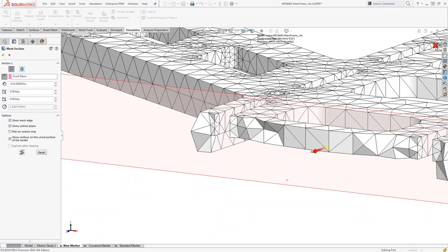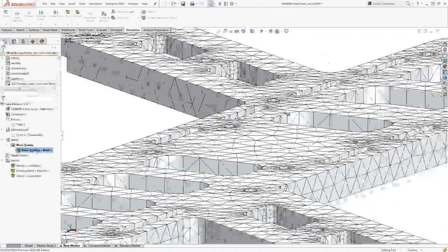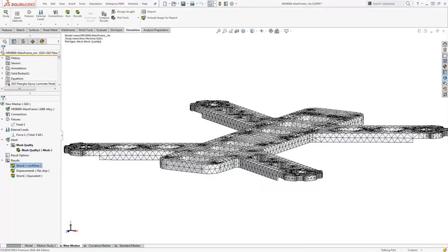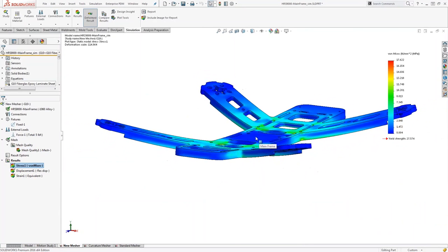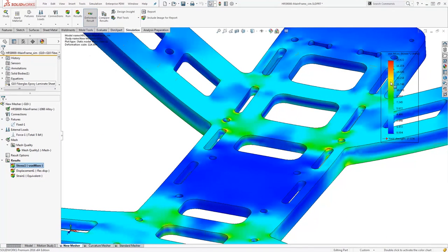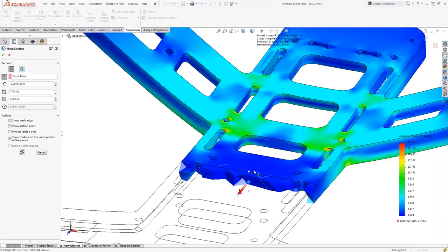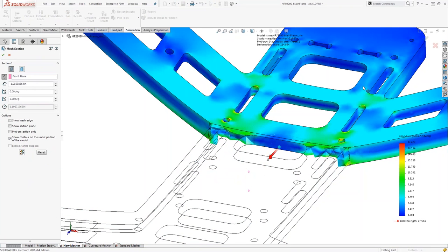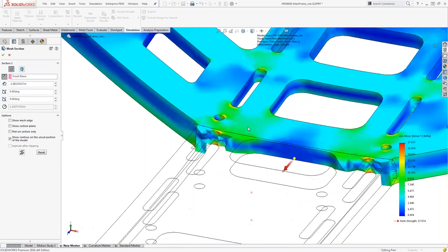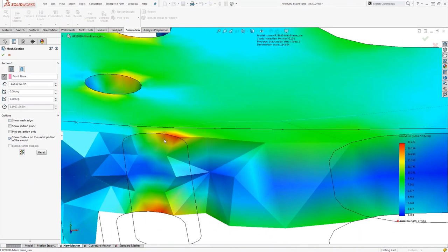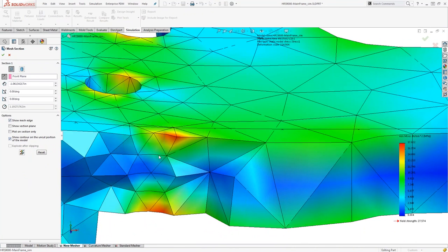Now, that was the first way. I did mention that there are essentially three. The second one is arguably similar to the first. However, we do overlay the mesh with the actual stress plot. It's not limited to just your stress analysis; you can do any kind of plot. If I right click on that, we can jump into a very similar tool for the mesh sectioning. So the interface and everything is exactly the same, except now it is overlaid over the analysis. So we can see our elements, as well as any kind of stress concentrated areas.